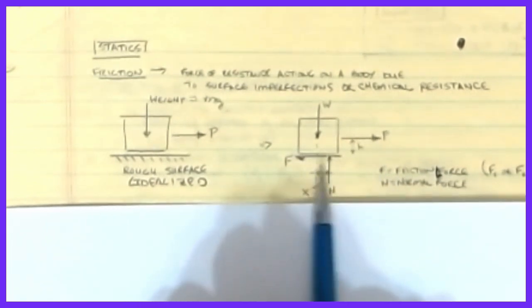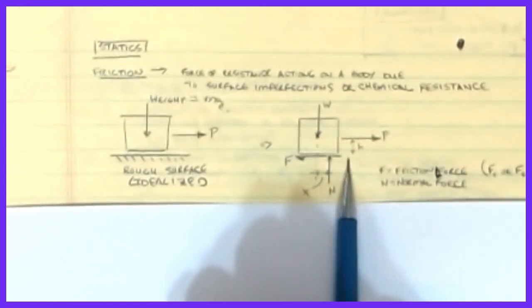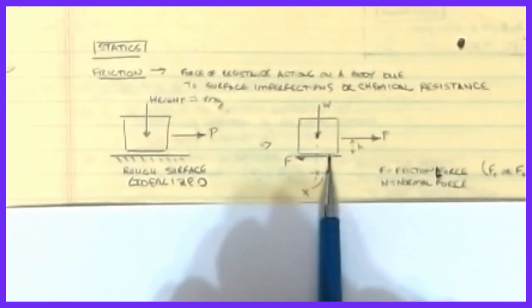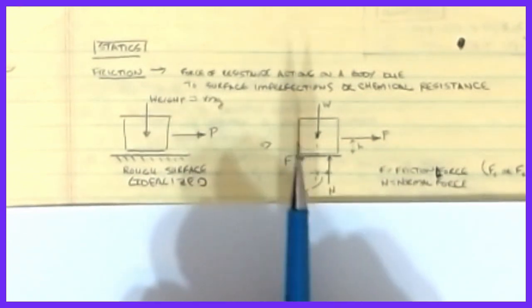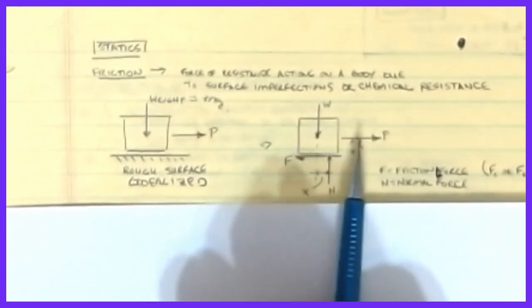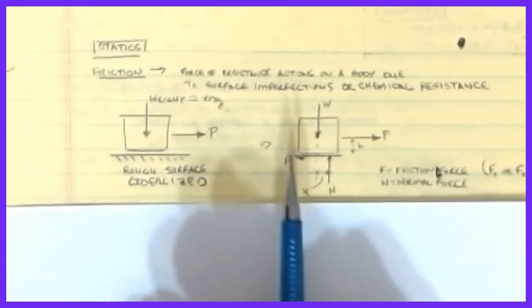This X starts to increase and this N starts to drift its way over from its original static position without friction to some new location. And it's in response to generate the moment that now N and W are forming a counterclockwise moment which will resist the one that P and F were causing. So that's kind of the basis.